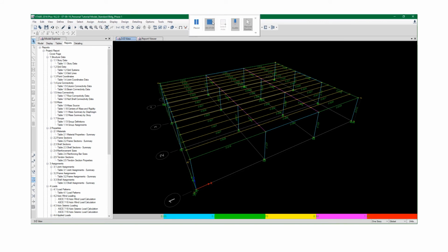With that, we end, and we've completed our direct analysis for this model. We could check things like deflection and sway and things of that nature and make sure that we're all good and go into the stability coefficients. ETABS doesn't do the same type of validation that RAM does for our RAM. So, for our direct analysis method, you have to do that yourself as an engineer using ETABS, and it's expected, and it's not a bad idea. Like I said, with RAM, you can't use it as a crutch. Even though it's giving you that information, you still need to ensure that it's right.